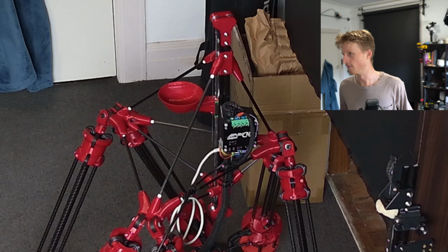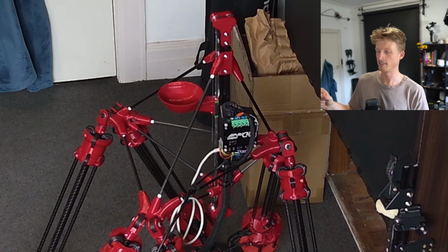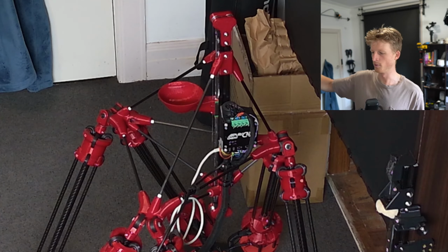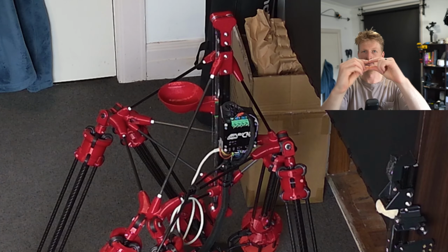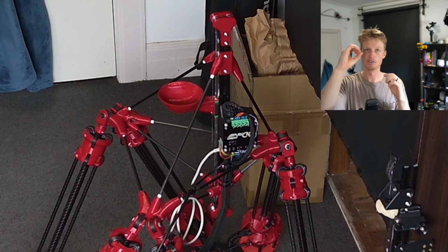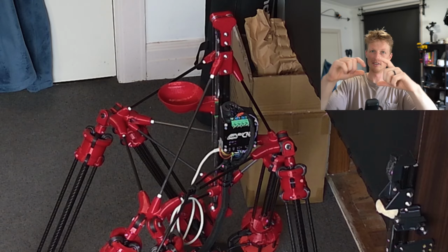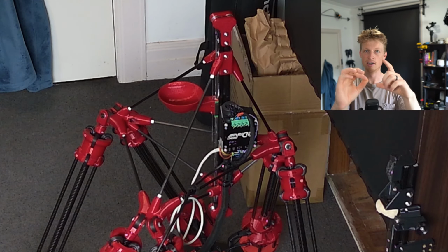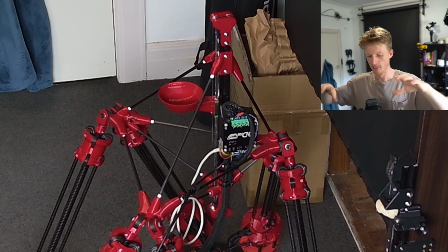However, Philip noted that by making these wrapped around cylinders, any viewpoint that we get is just going to be seeing a rectangle. And the QTM software is looking for circles, and it will try to find the centroid of a circle. And what this means is that when it sees a rectangle, it's probably not going to get the exact spot on center, but also if we rotate that cylinder around, then the center point is going to kind of be on the surface of that cylinder.